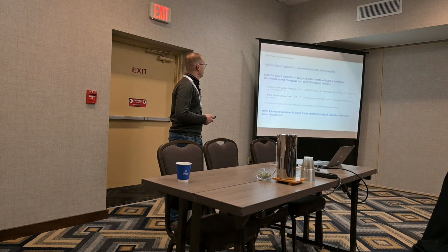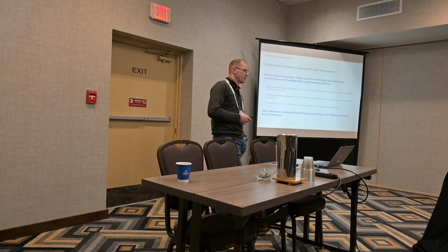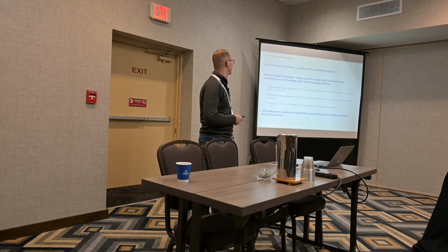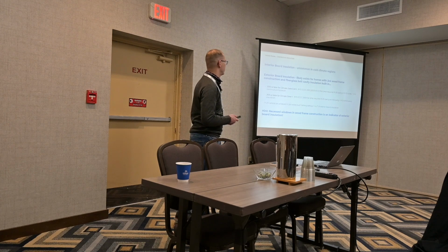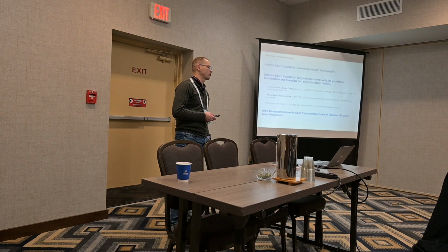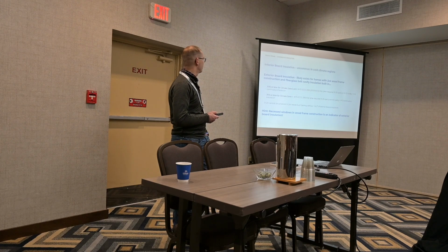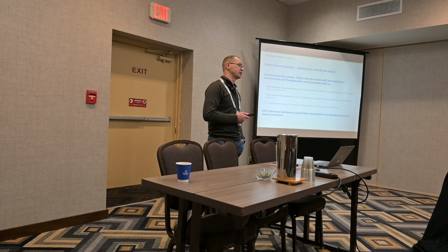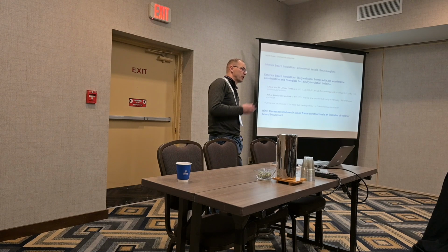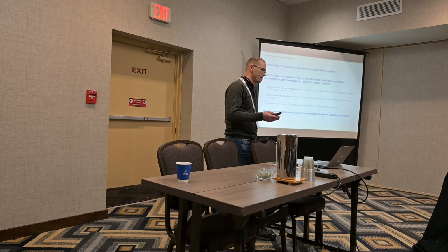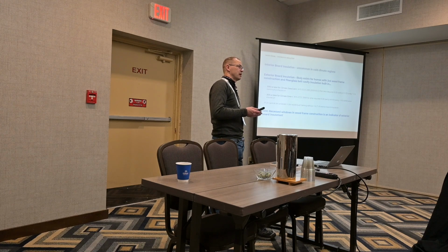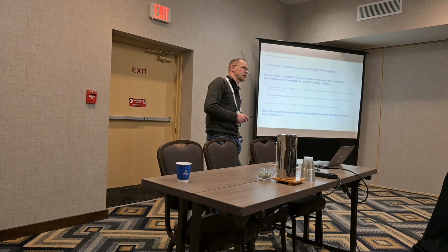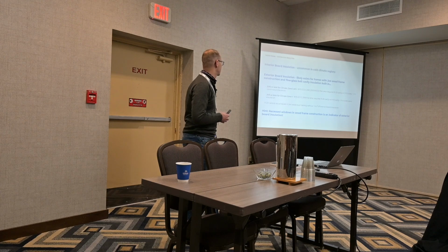Okay, so wood frame, interior board insulation is uncommon in the Northeast and cold climate regions. Exterior board insulation is much more common, likely existing for homes with 2x4 wood frame walls that are 2010 or later, and that's because of the changes to the efficiency code and building codes. As that went forward, the construction can still be 2x4 with R13 insulation, but you have to meet the efficiency code and add an R5 continuous insulation exterior board to the home. And that's where that came from.